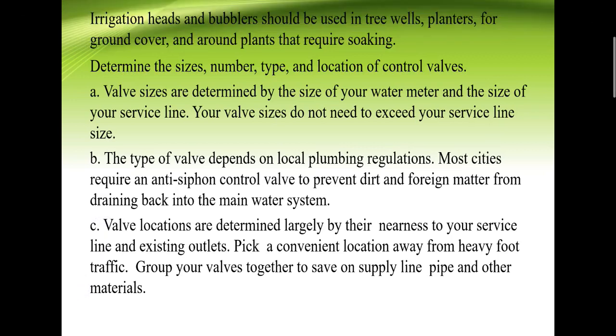And C. Valve locations are determined largely by their nearness to your service line and existing outlets. Pick a convenient location away from heavy foot traffic. Group your valves together to save on supply line pipe and other materials.